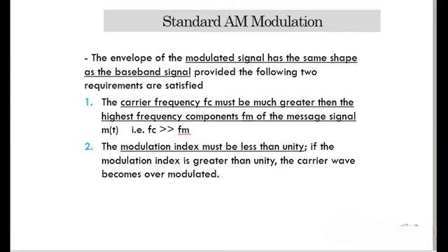Amplitude modulation: the message is carried with the radio wave, and in amplitude modulation the amplitude of the carrier wave is varied in proportion to that of the message signal, such as the audio signal. This technique contrasts with angle modulation, in which either the frequency of the carrier wave is varied, frequency modulation, or the phase, phase modulation.